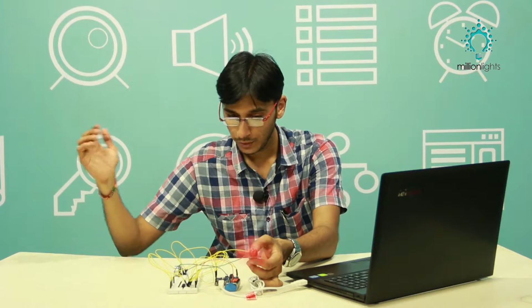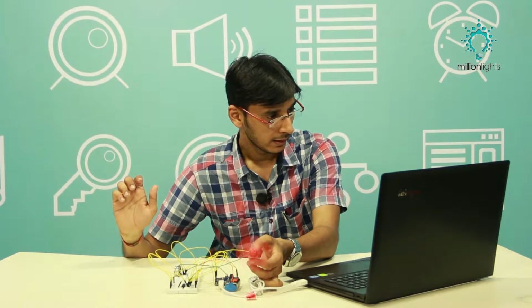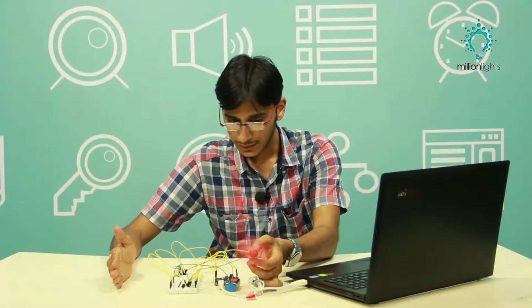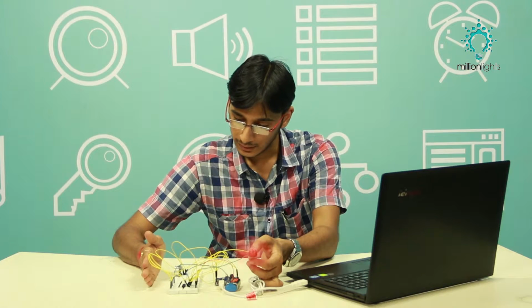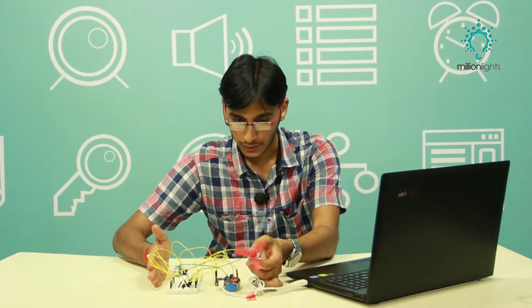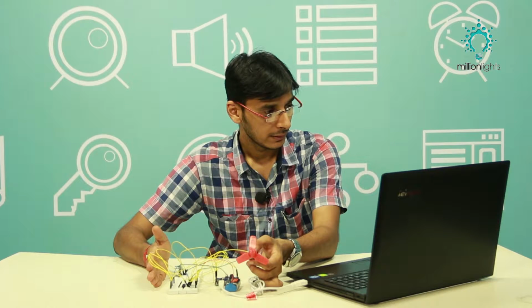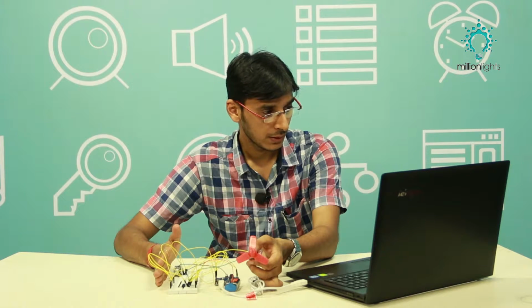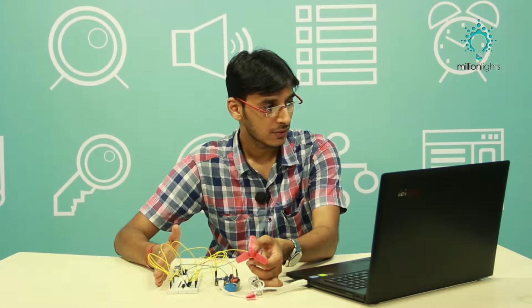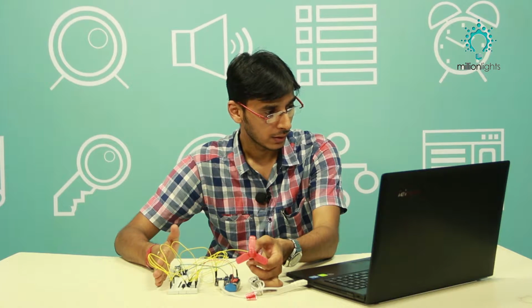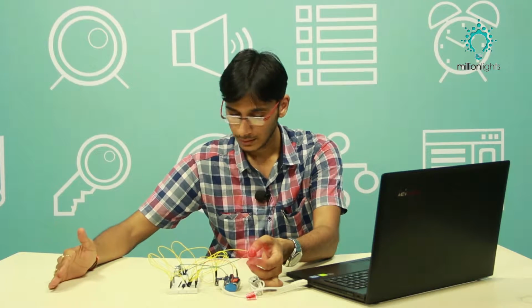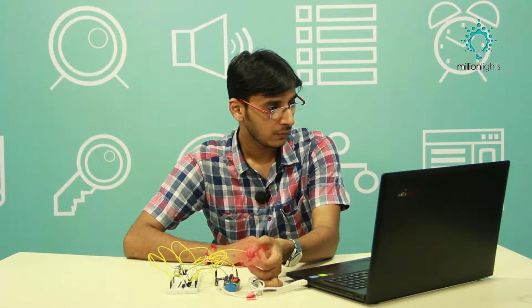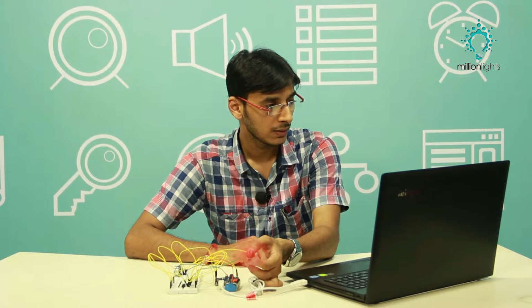Yes, and if I remove it, the speed gradually increases. Once again I'll place my hand in here, the speed should reduce. Yes, it's reducing, and at a particular point when I come very close to it, it will stop. Yes, now because the distance is 2, 3, it is getting a very low duty cycle and it's not even possible for it to rotate the motor, and if you remove the hand, it will start rotating. So based on the distance, the speed is varying. This is one fundamental thing that can be used for controlling the speed of our robots and other things.